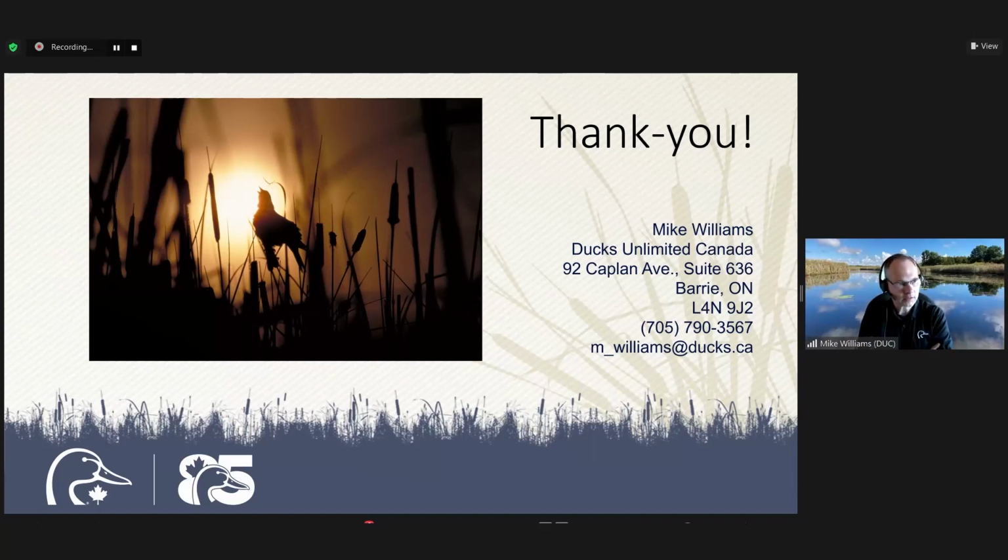Oh, that's an excellent question. So definitely the cattail. We're only using one species of aquatic plant in the surface water management ponds and the polishing wetland, and that will be Typha latifolia, or broadleaf cattail. The seed will be collected locally, so it will be a local species for sure. The other good thing about cattail is it's very robust and resistant to invasive species. So it'll keep other invasive species like Phragmites and loosestrife out.